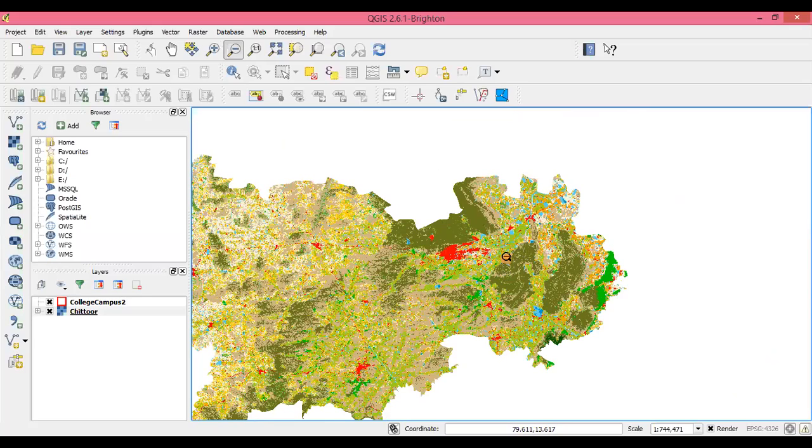Then you have to convert that daily rainfall data that has been provided to you. You will have to convert that into a rainfall intensity for a typical storm. Okay, not for a typical storm, for the highest storm that you are expected to receive, right? So what is the parameter that dictates finding out the rainfall intensity? Which parameter matters here? What do you think?